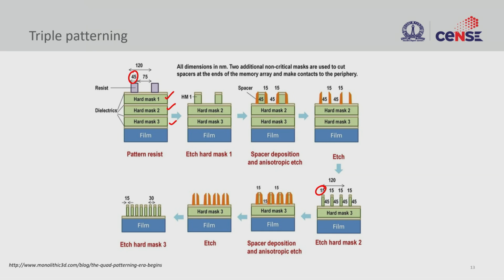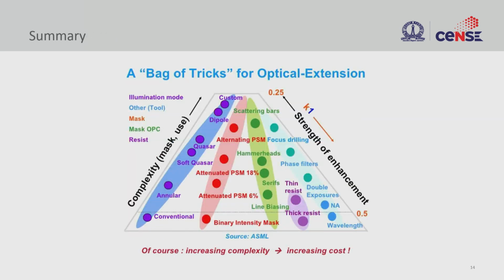The downside in doing all this higher level patterning is the cost of adding multiple layers, having alignment that should yield the kind of resolution that you are looking for, and all these criteria add up to the cost, right. That is the reason why this high resolution patterning by improving K always adds up huge in terms of processing cost. And in summary, this image captures how one could improve, right, the resolution of the optical lithography process, right,